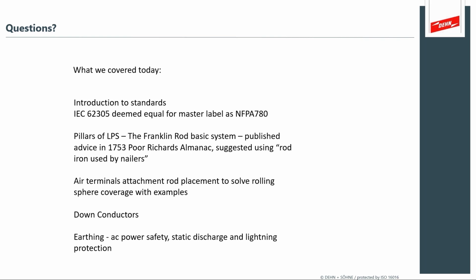Well, it's actually dependent on the lightning protection level that you've selected. The NFPA standard, I believe, is a little bit more relaxed because it talks about separation and bonding distance relative to the closest connection to the LPS system, which is a little bit misleading because that implies that the voltage only builds up relative to the next connection.